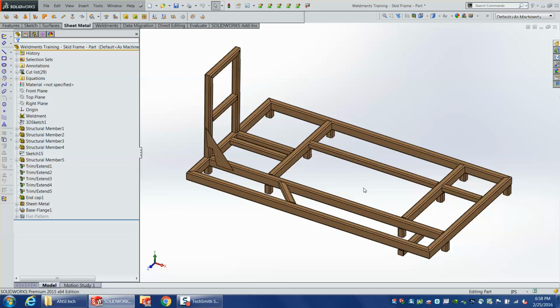Yeah, so he's given a suggestion. One thing they do is they use sort of starter files for weldments, and you could apply that concept to any kind of assemblies or parts that you use in SolidWorks as a standard thing. So if you have a certain arrangement that's common and a lot of people are just going to pull that and stretch it a little bit and change it, you have those files to start from. It's a good shortcut. That's what we're doing too. It does require maintaining those starter files, but in the long run, you save time because everybody isn't drawing from scratch. Anytime you can reuse data, that's a good practice.